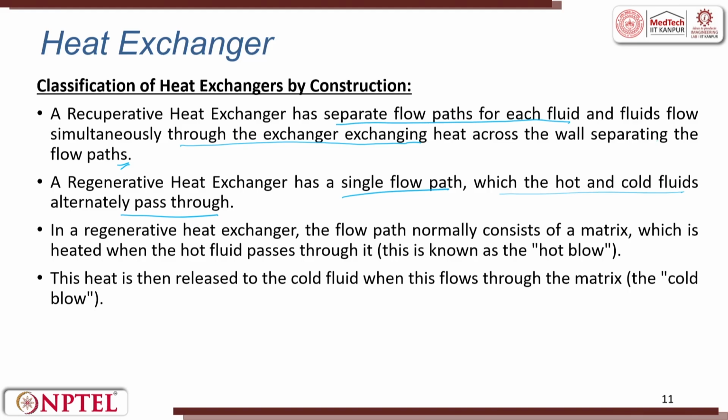In regenerative heat exchangers, the flow path normally consists of a matrix, which is heated when the hot fluid passes through. This is known as the hot blow. The heat is then released to the cold fluid when it flows through the matrix. That is called the cold blow. So, you have a hot blow and cold blow in regenerative heat exchangers.